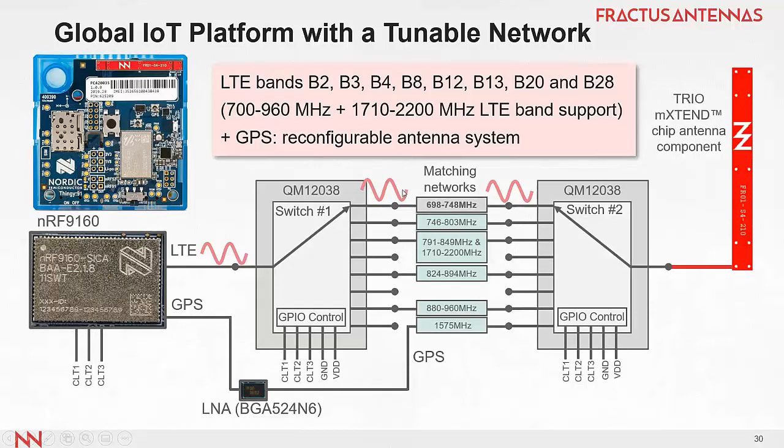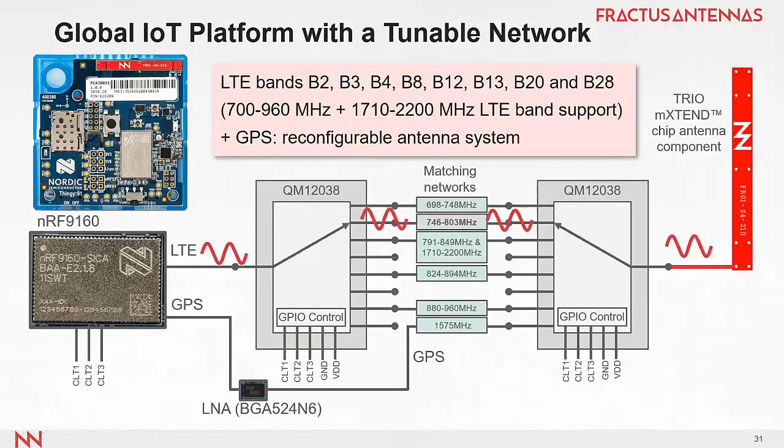So now we can design a particular matching network. We only match at this frequency range, which is much easier. With only 1 or 2 components, we can handle this bandwidth. In the end, this is the wave that goes to space, or also the wave that is incoming and received by the transceiver.